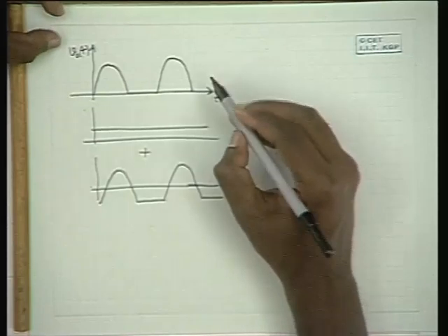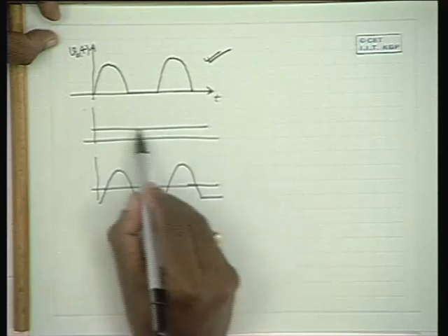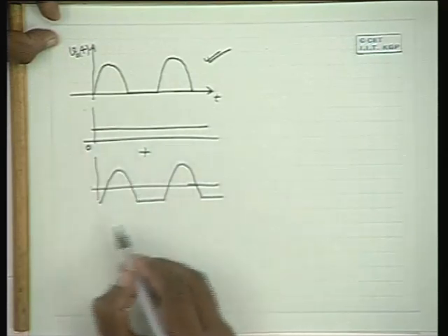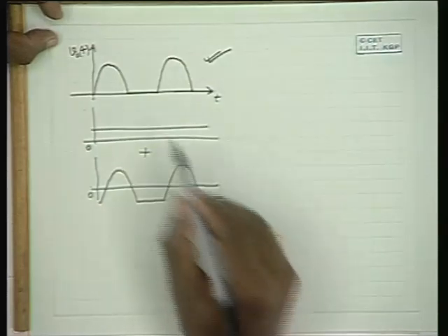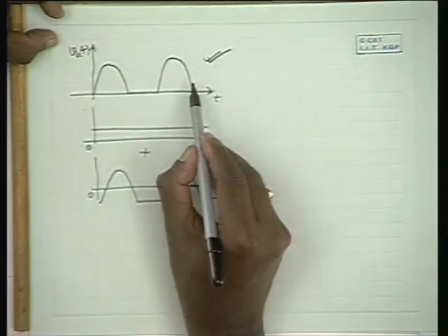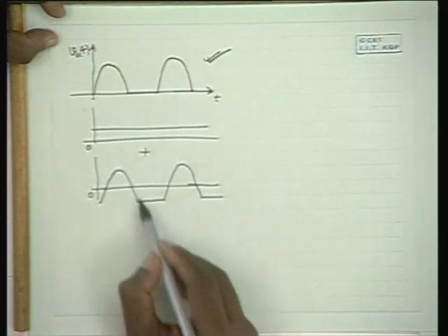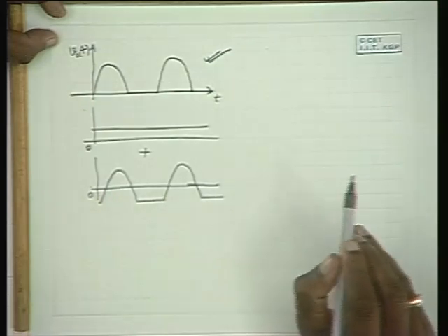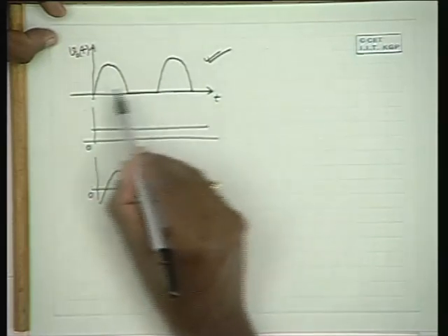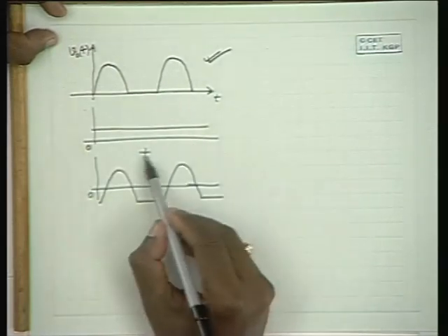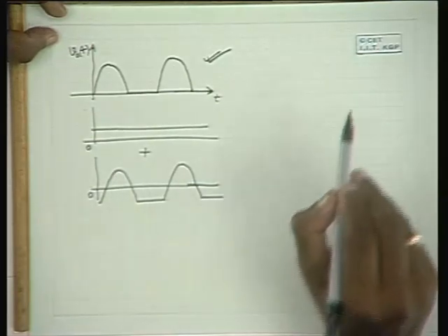So, please look at this. Can't this output rectified voltage be written as the sum of this constant voltage and this time varying voltage? If you find the average of this waveform, this is the average plus some alternating component with 0 average. So this can be expressed in this form. That means this voltage has some constant in it plus some alternating, positive going and negative going, component in it.